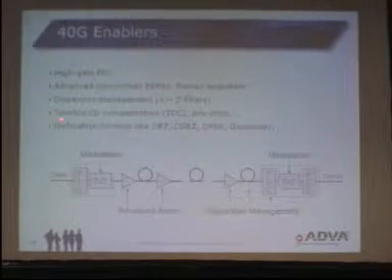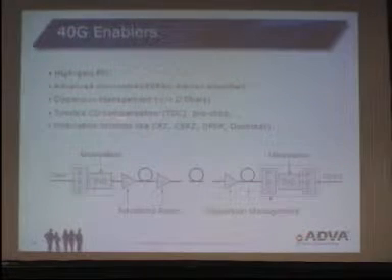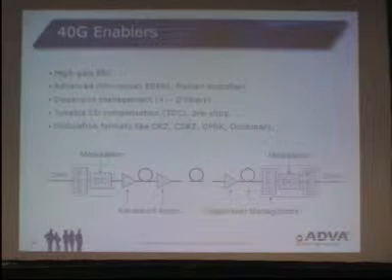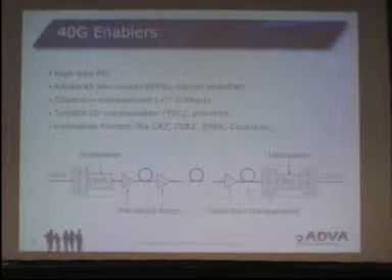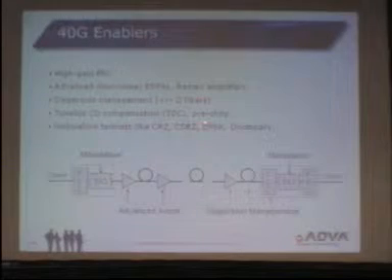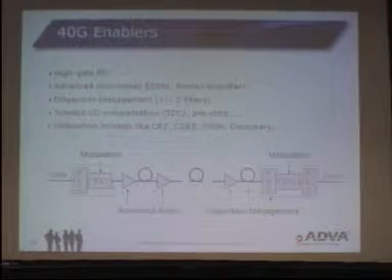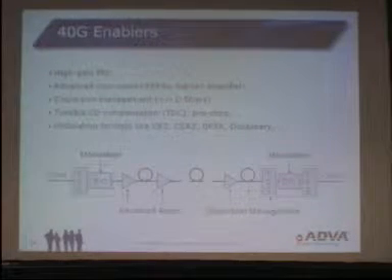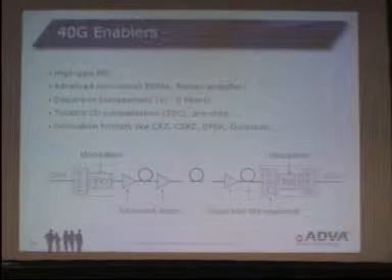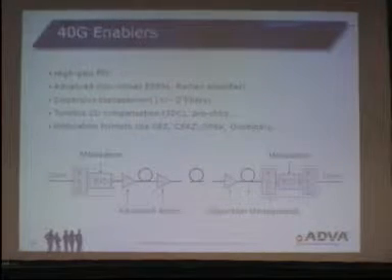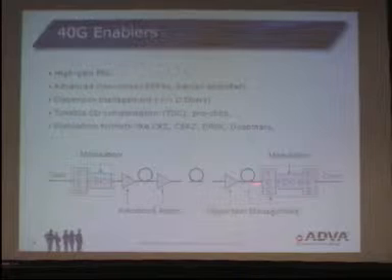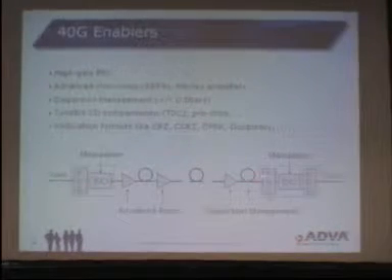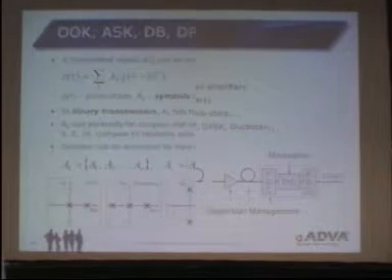In addition, we have to use these tunable chromatic dispersion compensators, maybe pre-chirp and other things. And we have to use other modulation formats or techniques rather than the old, well-known non-return to zero on-off keying. This would not work properly anymore. So in effect, it will be a combination of all, so using FEC, advanced amplifiers, dispersion management, tunable dispersion compensation, etc.